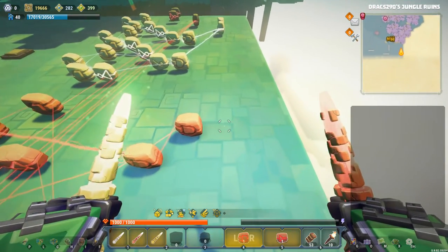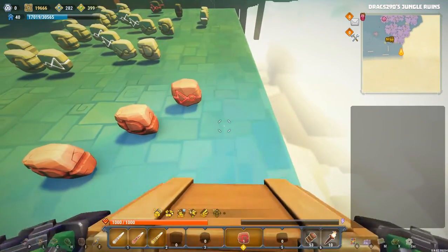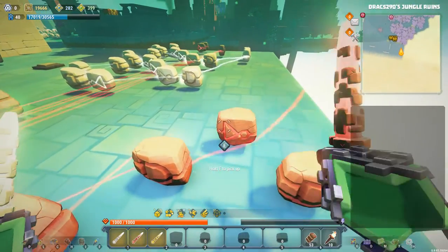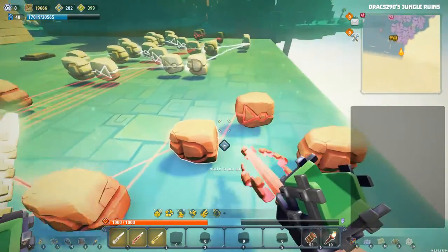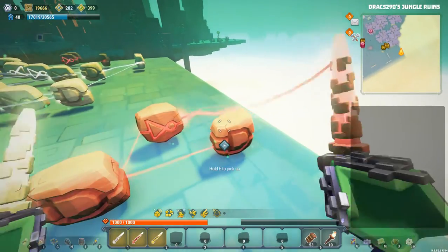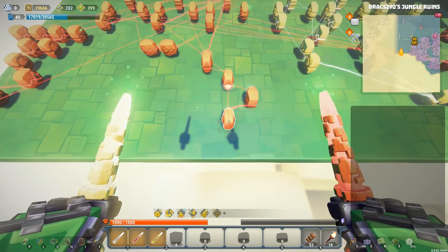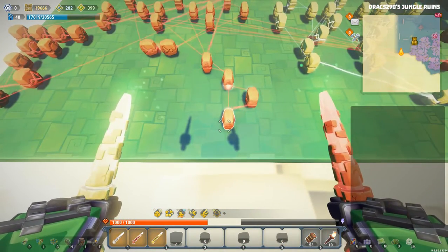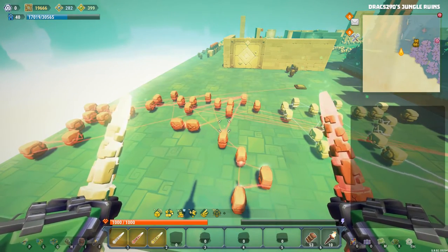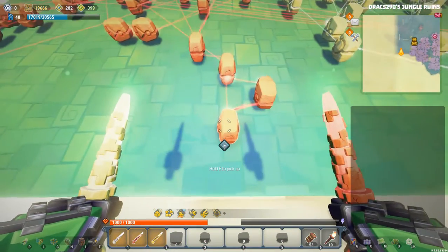So now we want to use a quick little rising edge pulse. So this is once again just a NOT gate and an AND gate like that. And we're going to hook all of these together. So the AND gate goes into the NOT gate and into the B side down there. The NOT gate goes into the A side, just like that. And so now we have a gate that is going to turn on and pulse once when all of those lights turn on together. Now this shouldn't happen realistically, but you just want to make sure that it's really, really not going to happen, and that's why we've got this little gate down here.